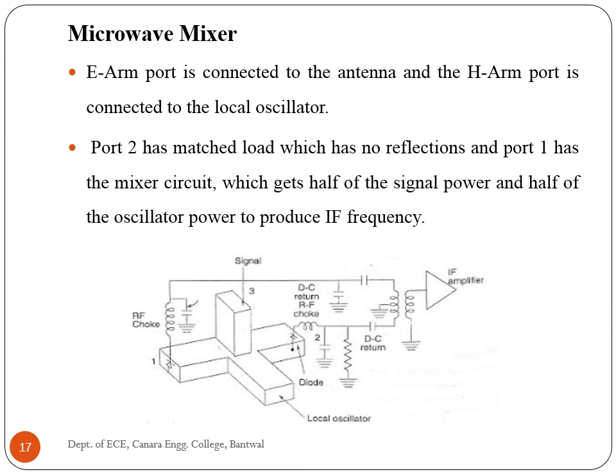These signals are mixed in the nonlinear diodes and produce IF signals in the collinear arms, which are out of phase by 180 degrees. Since local oscillator noise will be in phase at the diodes, this gets cancelled at the balanced IF input, whereas the IF signals are added up in phase for amplification in the IF amplifier.